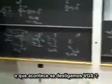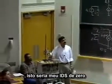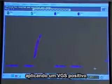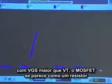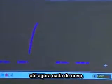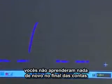And we also had some fun and games here. We said, hey, what if I turn VGS off? Boom. That would be my IDS of 0, implying that the MOSFET behaved like an open circuit between the drain and the source. I applied a positive VGS, more than VT, and it began to look like a resistor. Open circuit, resistor. Up to now, nothing new. You shouldn't have learned anything that's new until now in today's lecture.